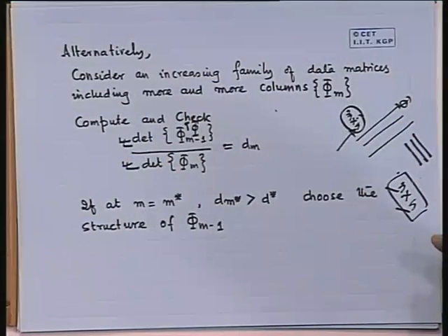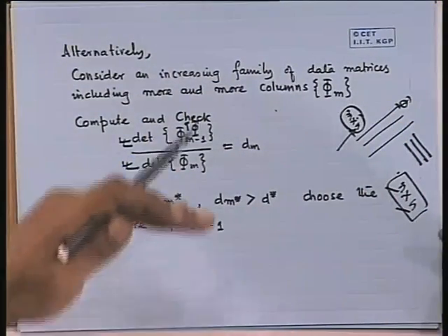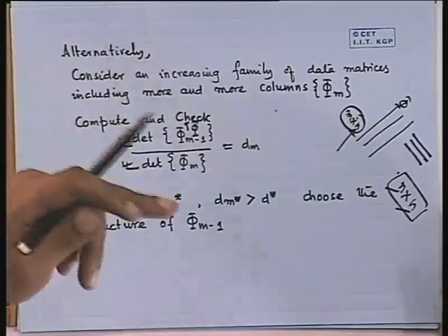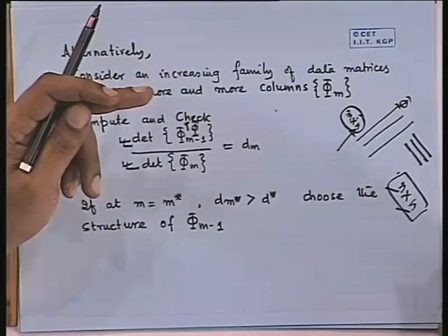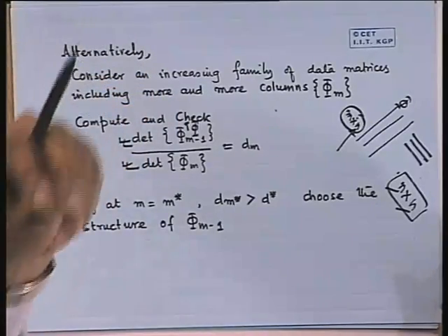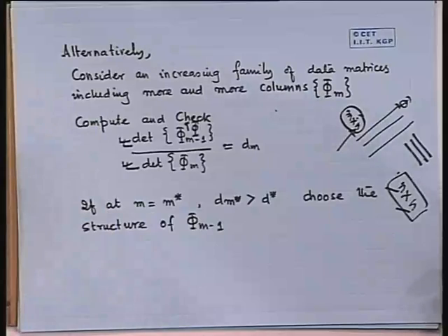So immediately that will show on this ratio. The idea is that you go on increasing the model order, every time compute the determinant of phi transpose phi, and check when the determinant is falling rather sharply. Stop at that level, don't increase.